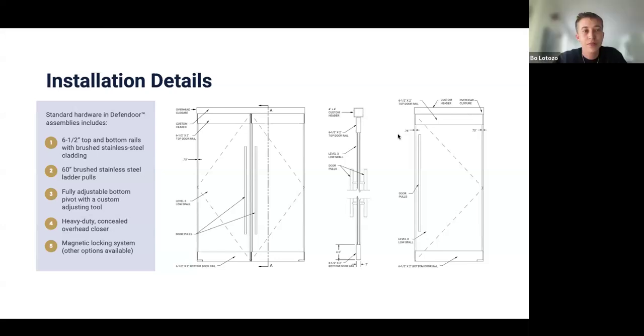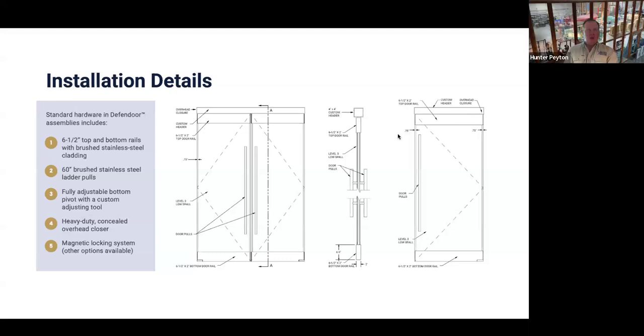All right, awesome. Do you provide shop drawings showing anchorage details and power supply locations for different wall conditions? So we would show where the leads for the power supply would come out. We don't get into low voltage. That is up to the client. But yes, shop drawings are a must.